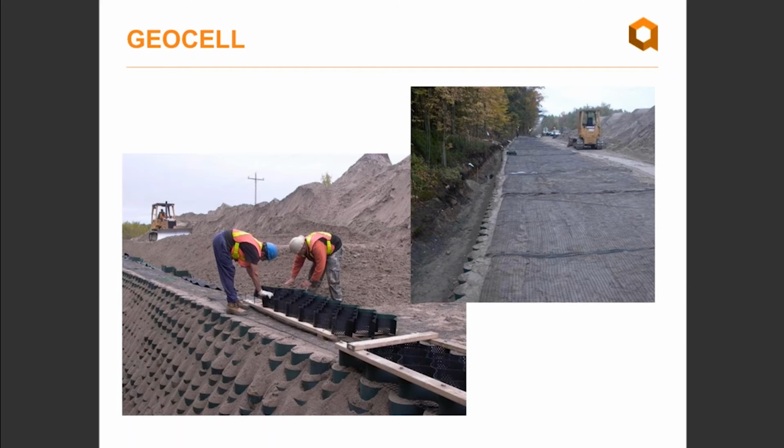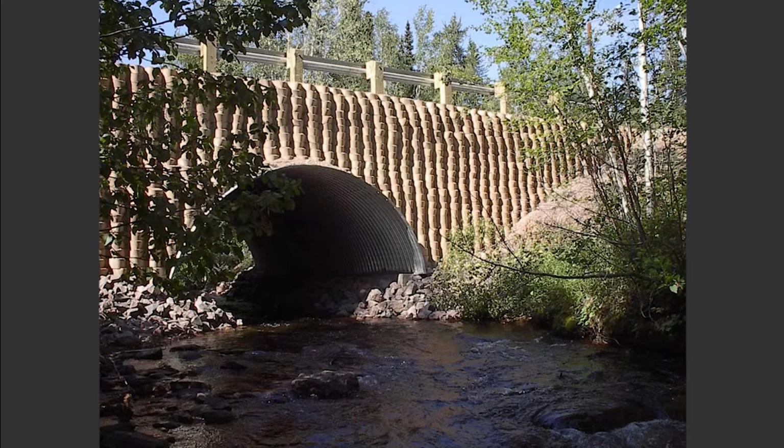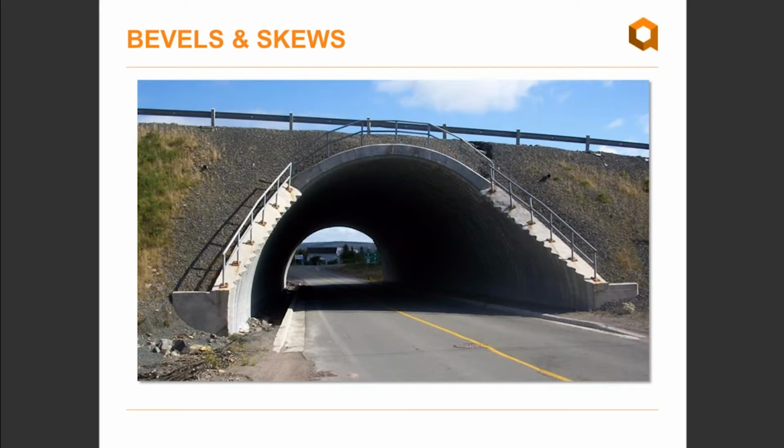So here's just a photo of the GEOCELL used in conjunction with a bridge plate single radius arch. All right, so lastly, in terms of end treatment, one of the most cost-effective options is certainly just a beveled end. So if you have the room or capability of doing this on site with just your sloped embankments, it can really be by far the most cost-effective and simplest option.